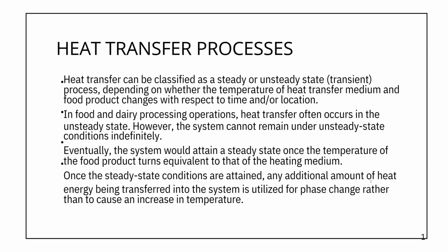Eventually, the system would attain a steady state once the temperature of the food product turns equivalent to that of the heating medium. Once the steady state conditions are attained, any additional amount of heat energy being transferred into the system is utilized for phase change rather than to cause an increase in temperature.